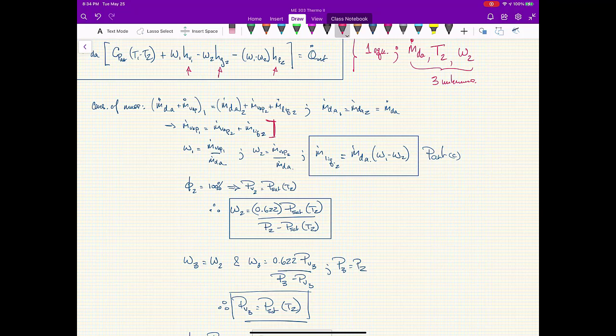So that therefore, the mass of liquid at 2, if I put the m dot vap2 on the left-hand side, is simply going to be the difference of these humidity ratios. And I showed you that result a little bit above already. But it pays here to highlight that final result, which is simply based on the definition of humidity ratio and conservation of mass. That's all that is.